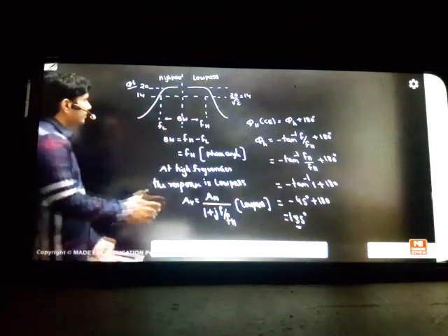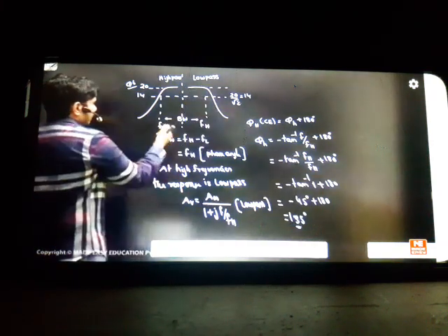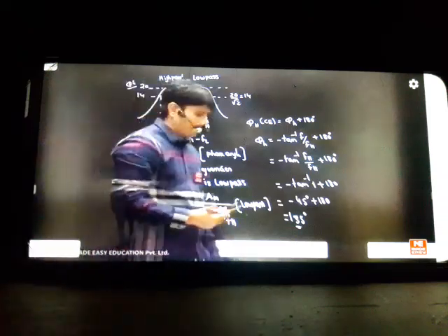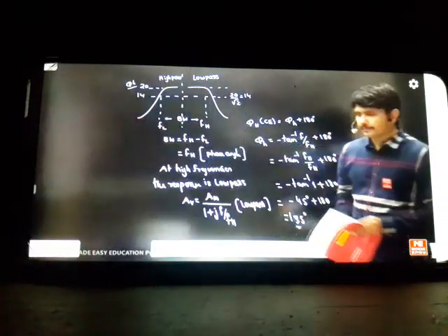Shavnidas, I hope you understood. This side a lower frequency it is passing, higher frequency it is attenuating. This side, higher frequency is passing, lower frequency is attenuating. So whenever you cascade a high pass with a low pass, we get band pass. High pass with low pass.